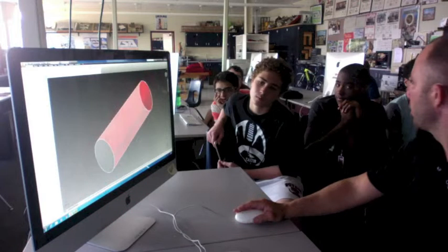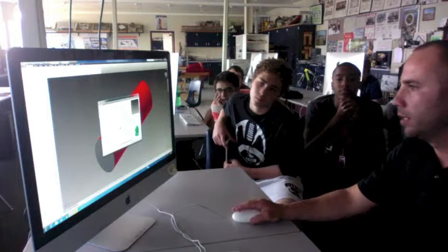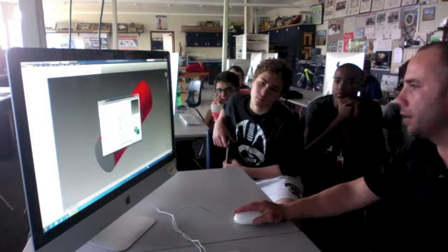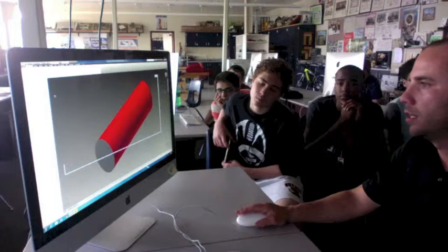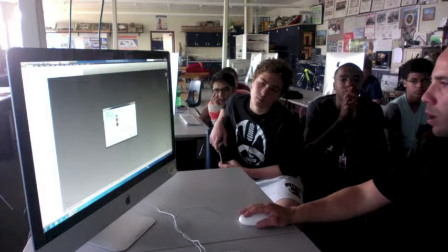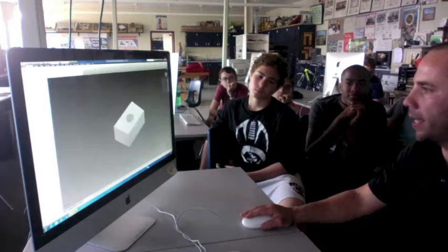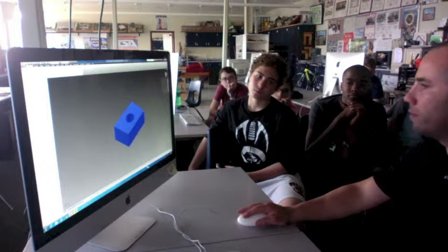Okay, we have 2 parts drawn, and now I'm going to go to File, new, and I'm going to go to my assembly file type, standard IAM, right? Now, I'm going to go to place, and now I have to pick from the desktop those two parts. So I'll bring my block 1 in first, and I'm going to hit open. I'm going to right click on my mouse, and I'm going to say place grounded at origin, and hit escape so there's only one of them there. So now I can't move that block. That's what I don't want to move that block.